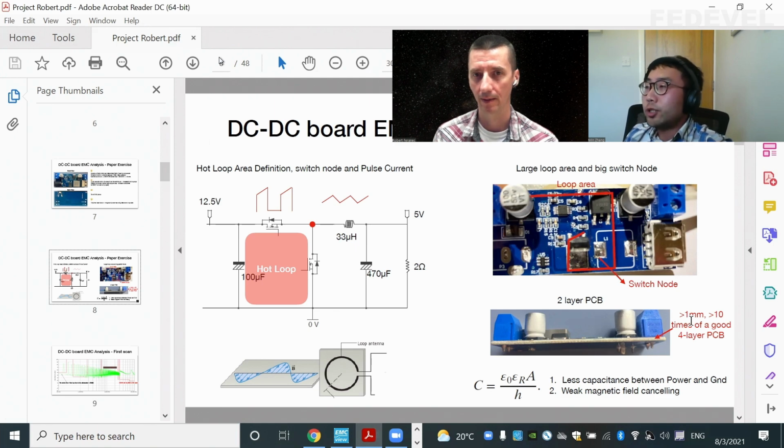Yes, for such a switching loop power supply design on the first layer, you can even have some cut-off area to segregate this noisy area, because all this area is quite noisy, as we just explained. It's dancing between your Vin and 0 volts. So you have a good separation between the noisy part and the quiet part on the top plane.